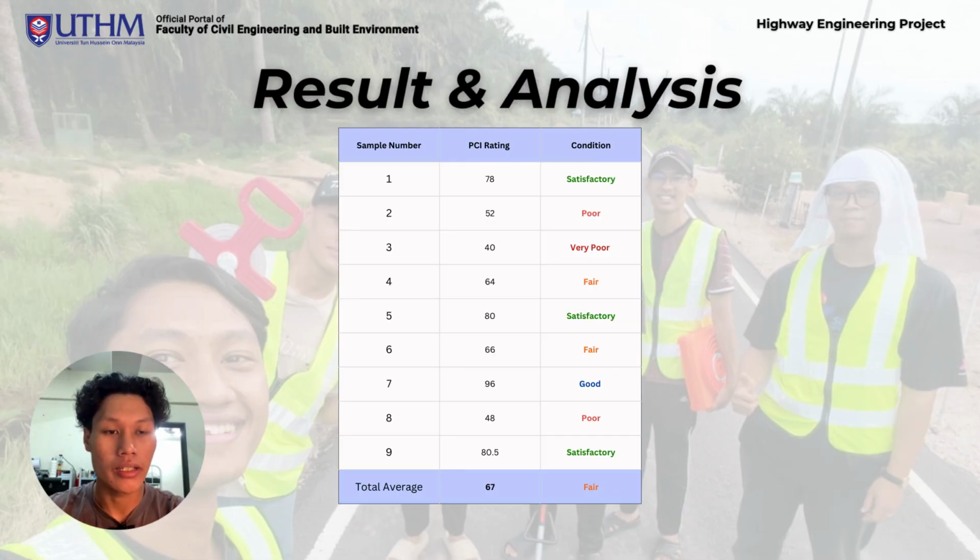Moving on to the result and analysis, this table displays the Pavement Condition Index, or PCI, for each of our 9 samples. The rating varies significantly across the stretch, ranging from a low of 40, which is categorized as very poor, to a high of 96, categorized as good. When looking at the road as a whole, the total average PCI is 67, which indicates that the overall condition of the 2 kilometer segment falls within the fair category.